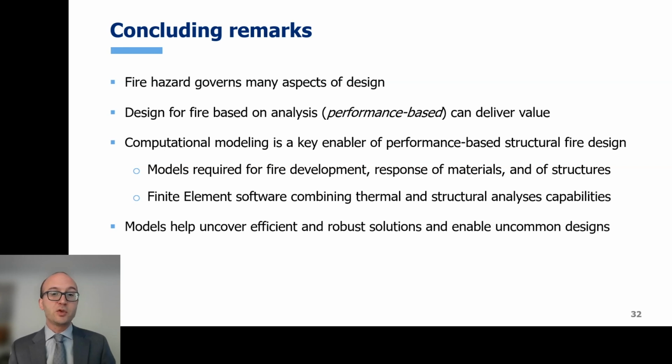It's also possible to study the shortcomings of prescriptive solutions. Notably, we think about geometric changes due to thermal expansion. When we are thinking about long span floors, for example, it can lead to issues that are missed by the prescriptive method. So these types of things are looked at carefully by structural fire engineers with numerical modeling.